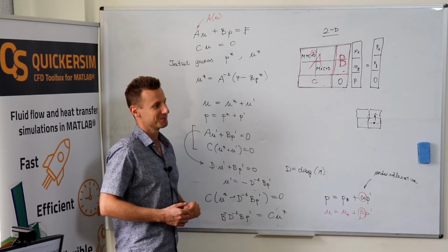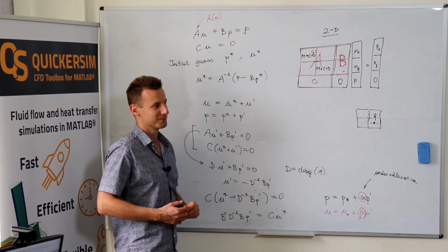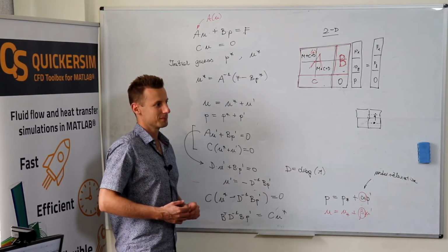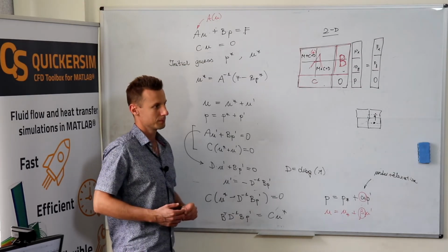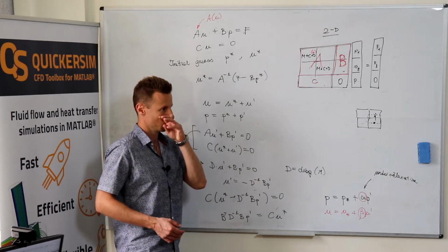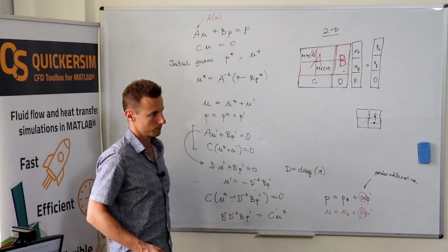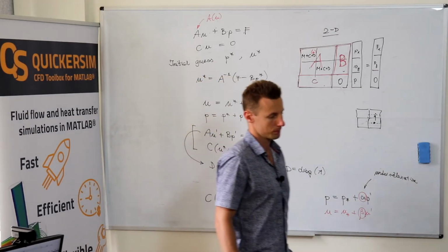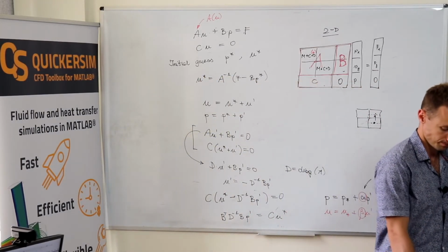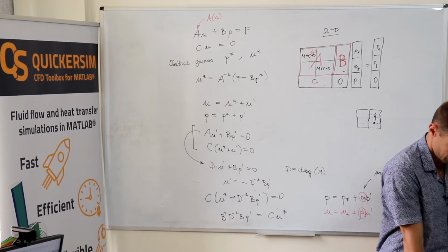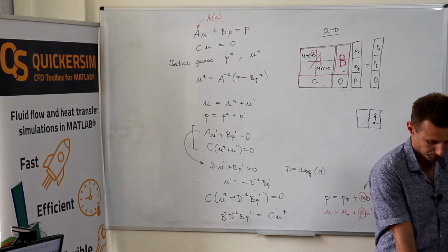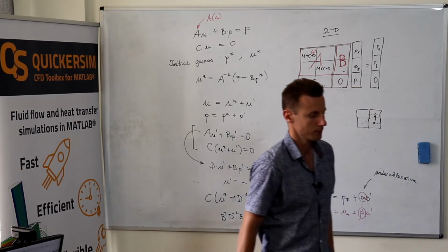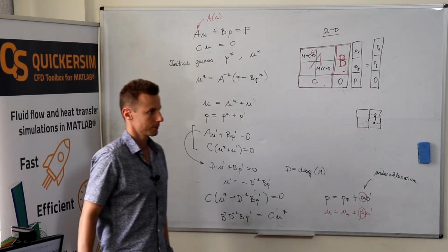In Fluent you specify which SIMPLE algorithm it is. You have SIMPLE and SIMPLEX. Yeah. But the default under relaxation factors for pressure and velocity are 0.3 and 0.7. You know, they're supposed to sum to 1. Yeah, and the difference, I guess, is that SIMPLEX adds some additional method for the skewness correction. So I think there will appear only some extra term in this derivation.